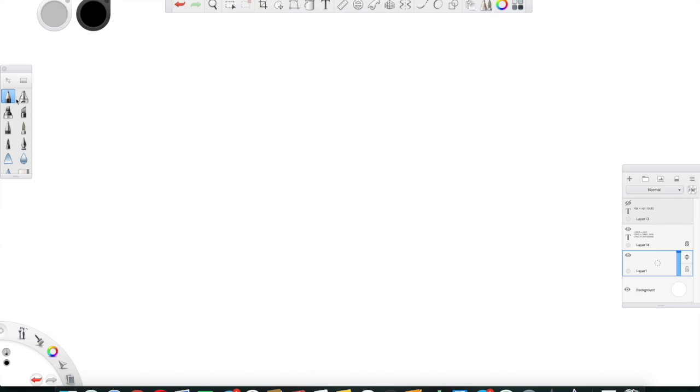So actually, we have here what? We have here the OREG, and I do not know the OREG value, and I do not want to affect or mess up the other bits. So the OREG is XX, XX, and here four other X's. I want to turn it on, so I need to send a high signal. I need to set bit 6 to 1.